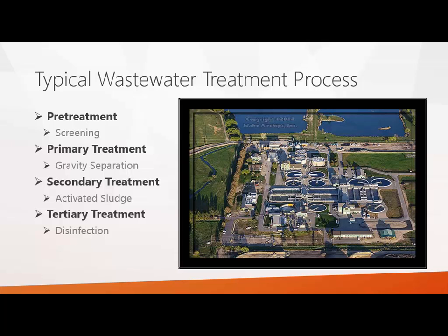As a general rule, the reason it's important is when you get to the disinfection or the activated sludge steps and the steps beyond the gravity separation, the dirt can actually mask biological agents. So if you have your diseases, whatever microorganisms in your wastewater, if the dirt's in there, whatever you put in to disinfect it, whether it be UV or chlorine, the dirt and stuff that's floating, say you have clay that is really difficult to settle out, it can actually mask that, and your tertiary treatment or your disinfection will not be nearly as effective.